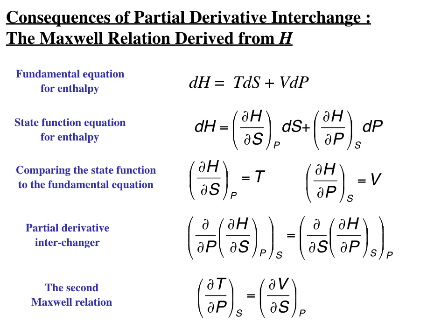This slide shows a derivation of our second Maxwell relationship. This time we will begin with enthalpy, and by combining the first and second laws, remember H is equal to U plus PV, dH is equal to dU plus PdV plus VdP. Then if we substitute the fundamental equation for dU into the beginning of that, we end up with dH equal to TdS plus VdP.